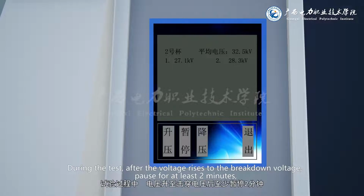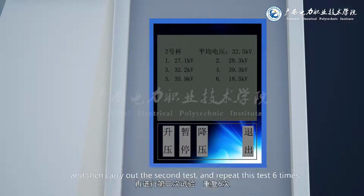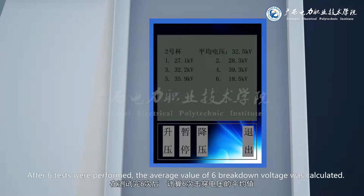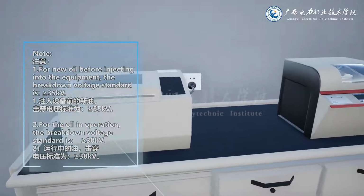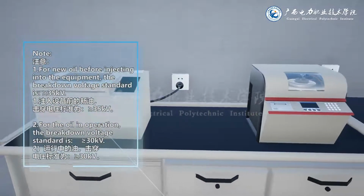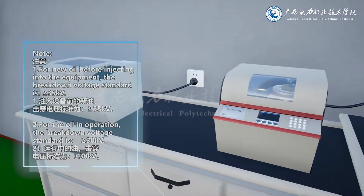During the test, after the voltage rises to the breakdown voltage, pause for at least 2 minutes, and then carry out the second test, and repeat this test 6 times. After 6 tests were performed, the average value of 6 breakdown voltages was calculated. Note: 1. For new oil before injecting into the equipment, the breakdown voltage standard is greater than or equal to 35 kV. 2. For the oil in operation, the breakdown voltage standard is greater than or equal to 30 kV.